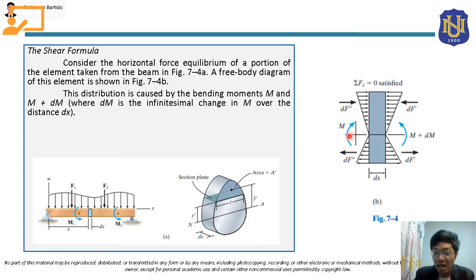Let's say ito yung neutral axis. So, above this neutral axis, class, the stress will be compressive. Kaya makikita mo dito, class, ganyan yung direction ng stress distribution natin dito. And on the other hand, dito sa baba, class, it will be subjected to tension. So yung stress distribution natin dito, it will pull away the cross section, kumbaga. Kaya pahila yung stress distributions natin dito.